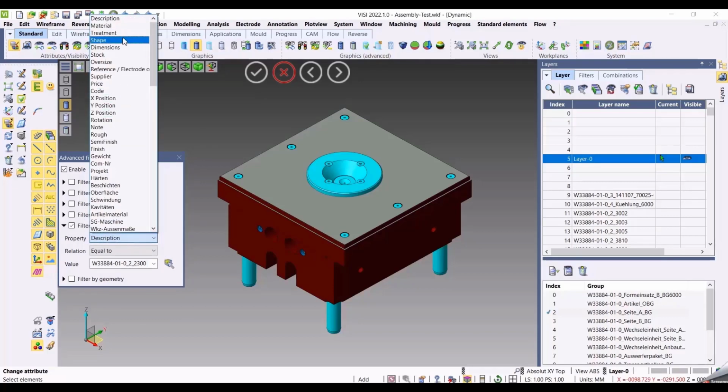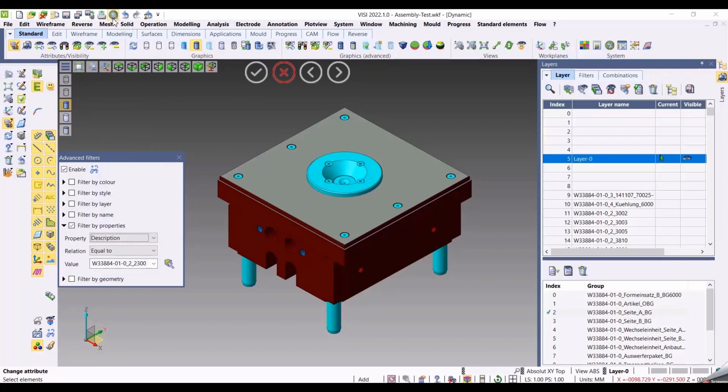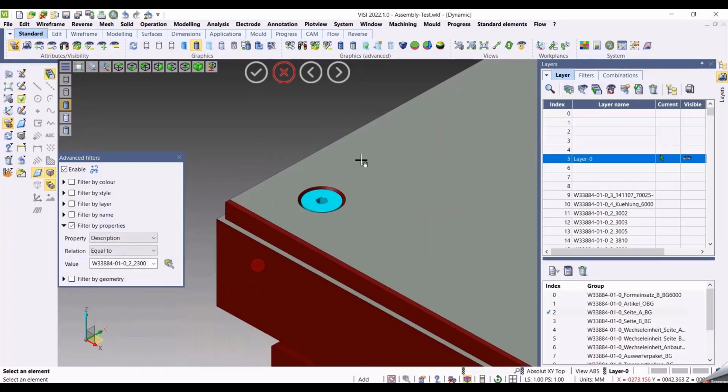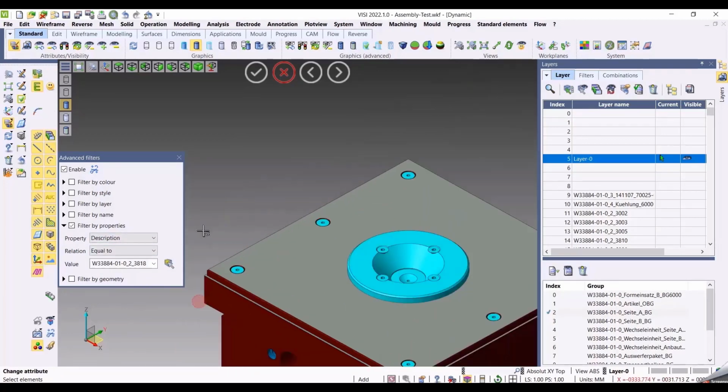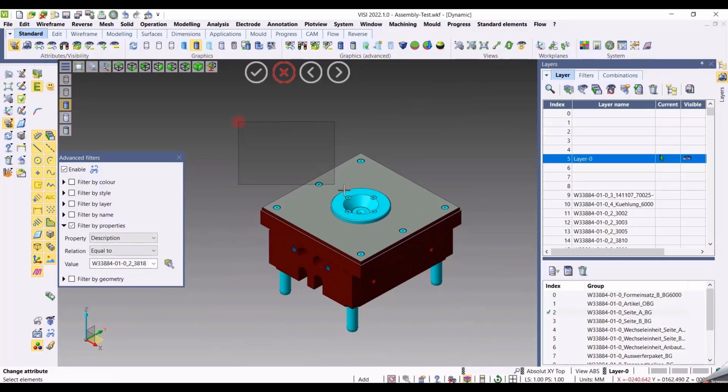If we select by specific property, inside the parts list, you could choose whatever field that you want it to only select from. If you say get properties, you choose the specific item for the properties you're going to get. And then if you use the select all entities or select properties again here, it only is going to allow me to choose whatever is selected in that. As you can see, I picked that component. It only chooses that component based on the properties that I've specified here.